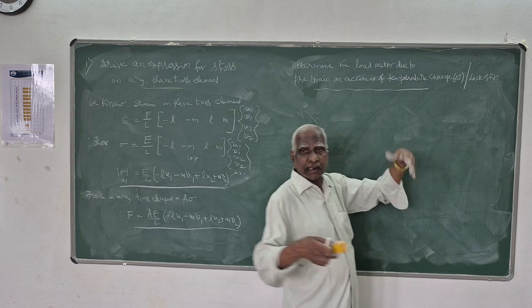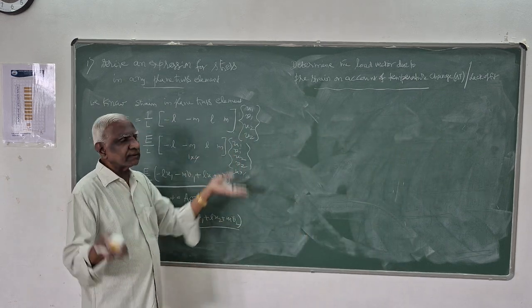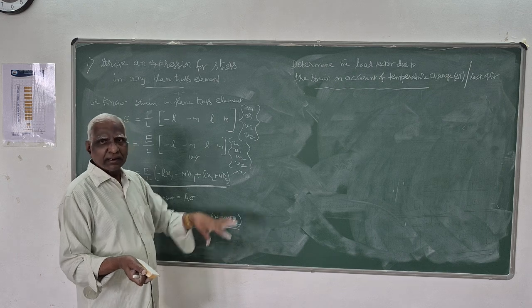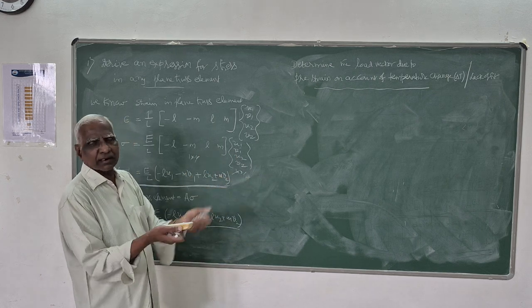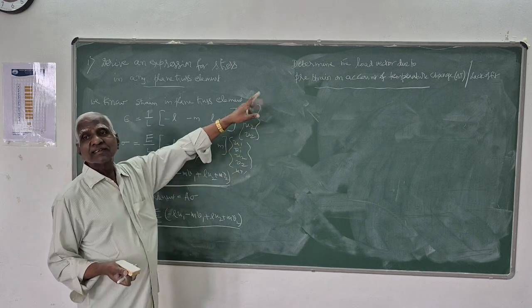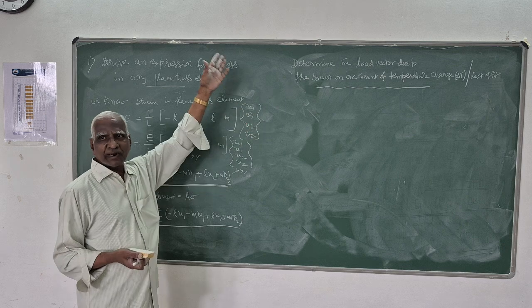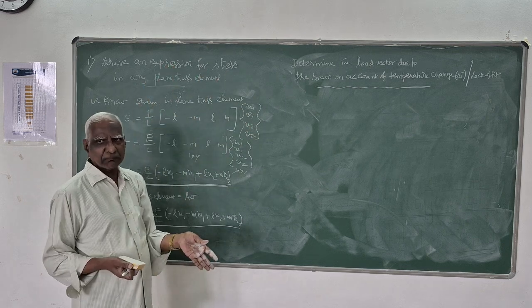Or it may be temperature change. There may be temperature variation, increase in temperature or decrease in temperature. In such cases, there will be expansion of the members. Due to that, some pre-strain will develop. And because of that, how to find the corresponding load vector.